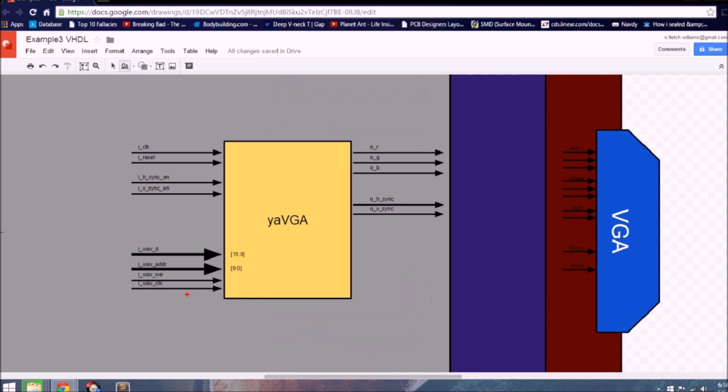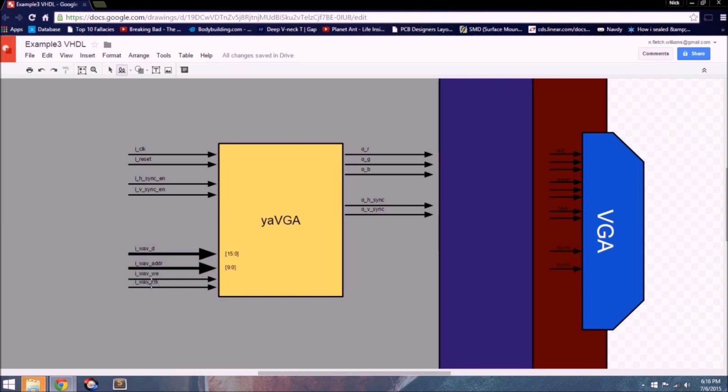And then the clock, you can kind of drive that with whatever. Ideally, you would synchronize this clock with the waveform, but in my experience, you can hook this right up to the same clock as here. Now, the outputs make perfect sense because they just hook up straight to the VGA port, which uses horizontal sync and vertical sync. I'm not going to go over the protocol of VGA because there are so many tutorials online that cover this. If you're interested in learning how the protocol works, you can easily Google search it online. But just know that I'm going to hook up this single red signal to all these reds, this green signal to all these greens, and this blue signal to these two blue signals.